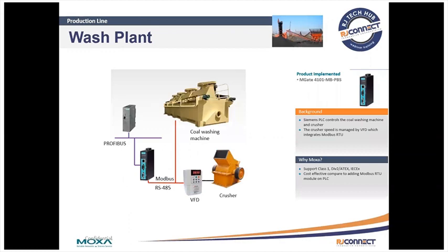Here's a wash plant example where the plant control system was using Profibus, but the variable speed drive for the coal washing machine was Modbus RTU, and they also needed support for Class 1 ATEX approval for high explosive or explosive environments.